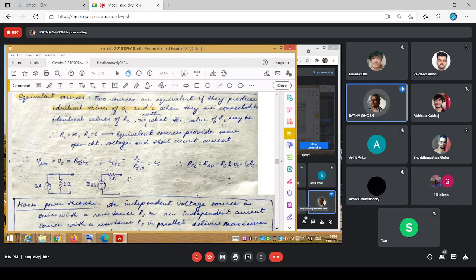Across those two terminals, you affix different values of resistances, or a rheostat or a potentiometer depending on how large the circuit is, and you keep changing the resistance value. Whatever values you get, short circuit, open circuit, or interim values, assuming linearity holds, you can map back.